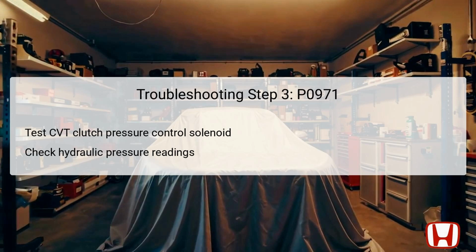If hydraulic pressure is too high or too low, this could indicate a failure within the solenoid or a related hydraulic component. Documenting any discrepancies will be useful for further analysis and may point toward the necessary corrective actions needed. A successful test would indicate that the solenoid is operational, while any issues would necessitate further investigation.